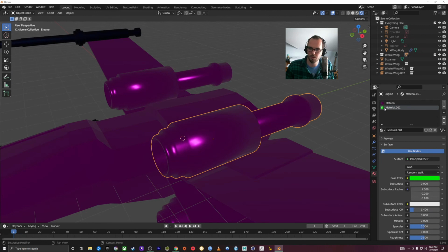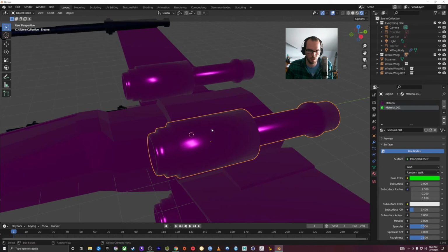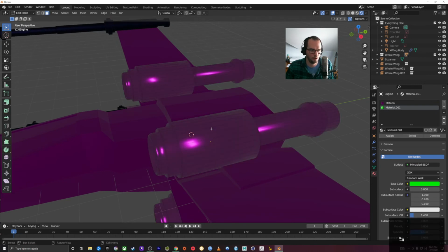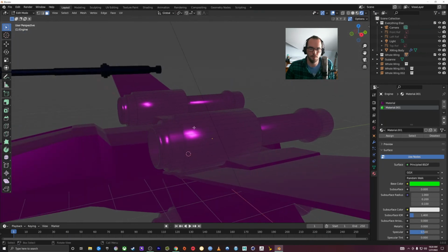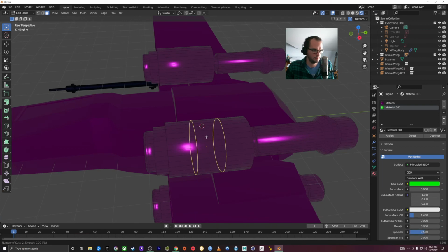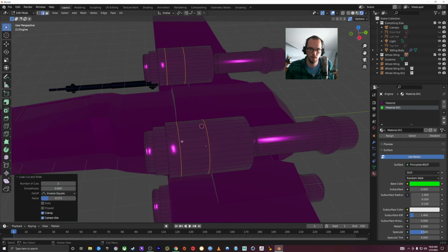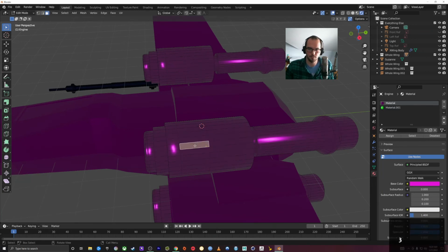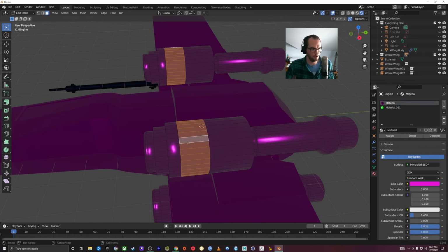So we can see we've got the pink one and the green one in here, but nothing has happened on the object. So what I can do is go into edit mode by hitting the tab key. Actually, let me do Control R, and a middle mouse wheel up like this, add 2 loop cuts. Maybe slide them like this. Then I want 3 for face select, and I want to click 1, alt click to grab that loop.